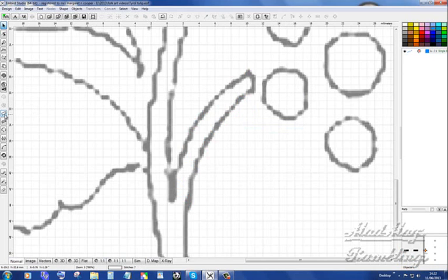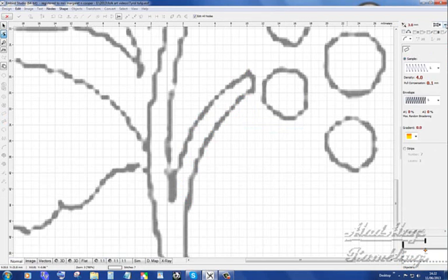And now we'll look at the C option. Now, the C option is fantastic. Now, I want you to look up here and watch what happens there. If you know what you want in the way of thickness, once you've set your thickness, that thickness will be the distance between your first node and your second node. And here it is at 2.4 millimeters.